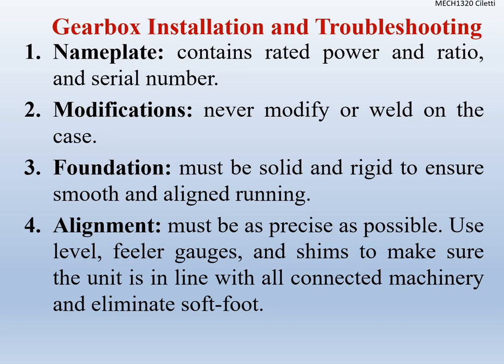Gearboxes, planetary gears are gearboxes as well. All right, so gearbox installation and troubleshooting. Every gearbox is going to have a nameplate that contains the rated power, ratio, and the serial number. Okay, you will never modify a gearbox. You're not supposed to modify them or weld on the case at all, because you can do a lot of damage to things.